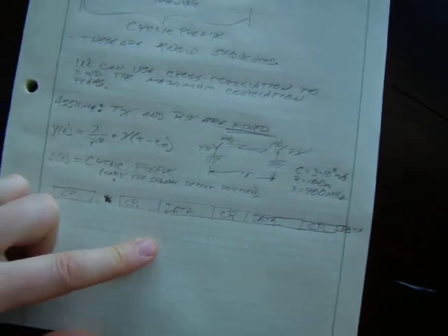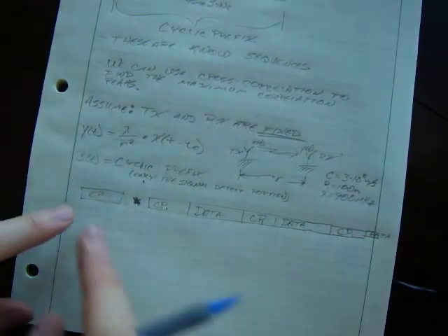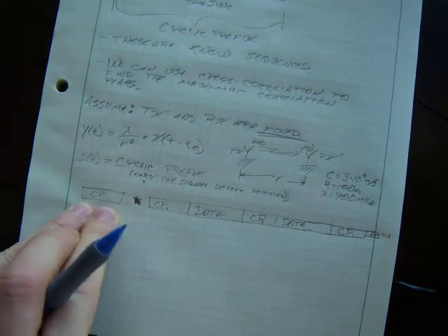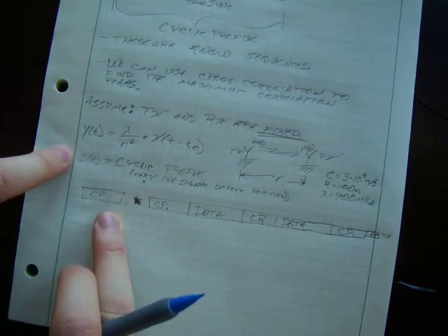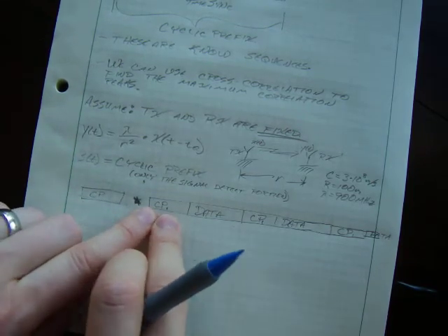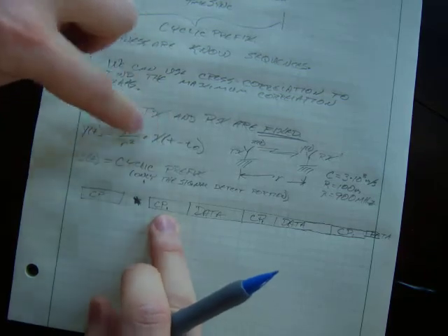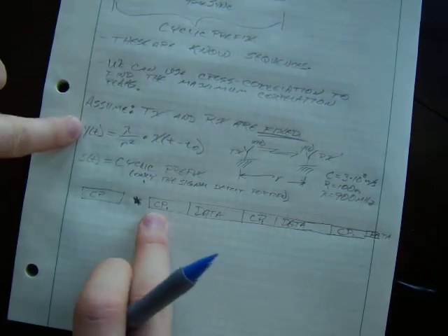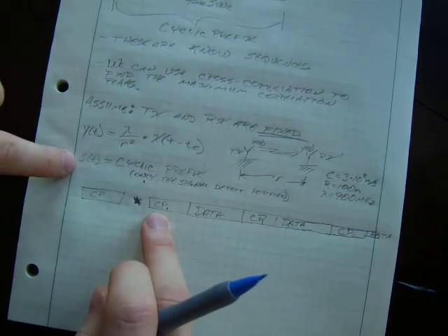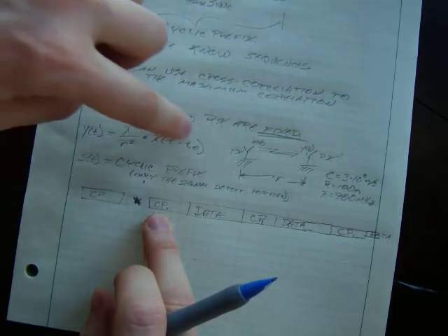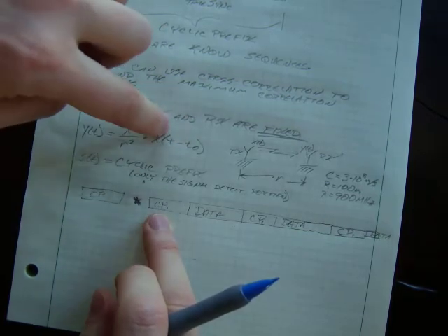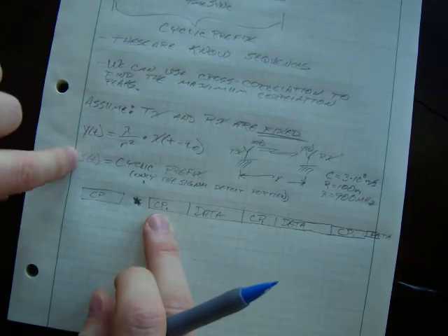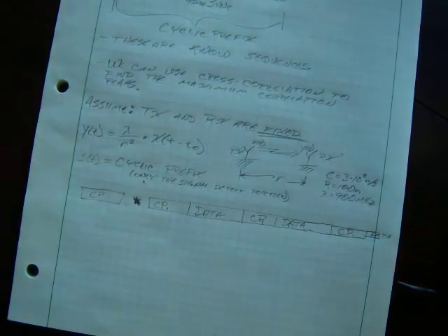So this is conceptually what we're going to try to do. We've got this reference cyclic prefix, which we're going to call S of t, and then we have the actual cyclic prefix that is going to be the Y of t, the received signal, and it's going to be some attenuated and time-delayed value of S of t, because X of t and S of t in this example are the same code.